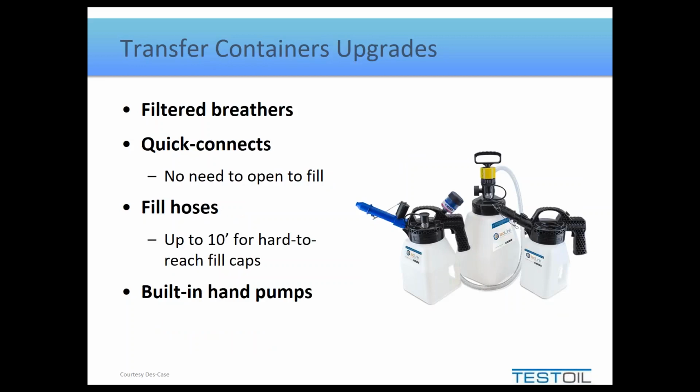Now, when we talk about these containers, one of the major flaws most people point out about transfer containers, like the ones previously pictured, was the only way to fill them is to remove a giant cap. You can upgrade them. This is a different manufacturer that makes similar containers. It has everything we just talked about: spouts, transparency, sealing, etc. But it also has quick connects, so those can be filled directly from filter carts and filter pumps without having to open up the top. So there's definitely a wide range of products that exist out there. They do help prevent further contamination and help encourage additional filtration along the way.